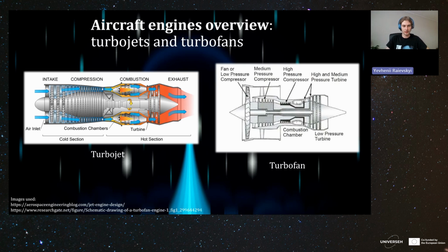The next section is here. It's called the turbine, which also has some blades, almost the same as in the compressor section, but they are thicker because here those blades need to withstand very extreme conditions compared to those blades. Here the gas is very hot, and the pressure is very high compared to this section.